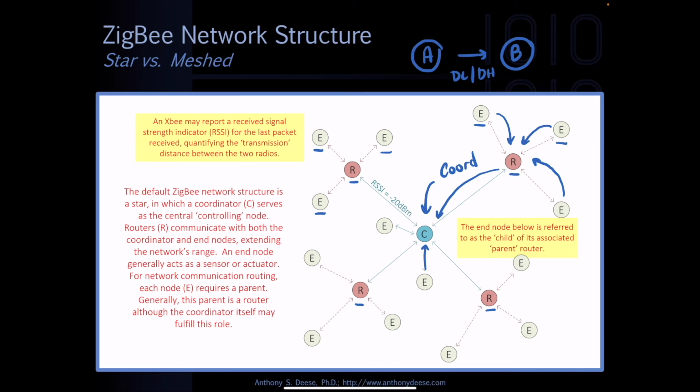So my goal here is simply just to lay out the general structure of the star network, which we'll be using for a large number of the examples. We have 3 different types of radios, just to reiterate: coordinator, router, and end node. And this coordinator right here is generally going to communicate with the external world or with the internet. And that's why this job will generally be filled by the X2 or something similar to the X2 connect port, which is the ZigBee to Ethernet gateway.